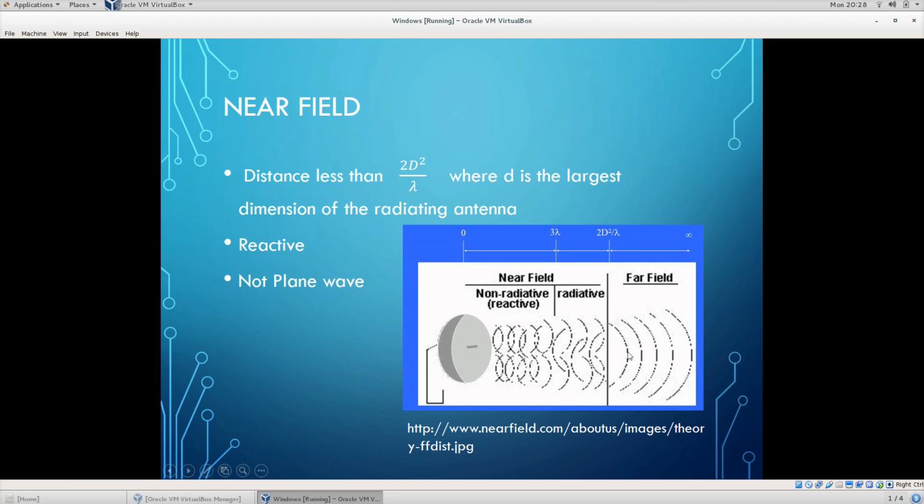The idea behind a far field antenna is that the waves have gotten to a point where, as they're radiating away from the source, this line right there is effectively a wall, meaning that the phase front of the waves is planar to the surface of whatever you're measuring out here in the far field. This is why we like to measure antennas in the far field: we can assume planar waves, which means we only need a single point to measure.